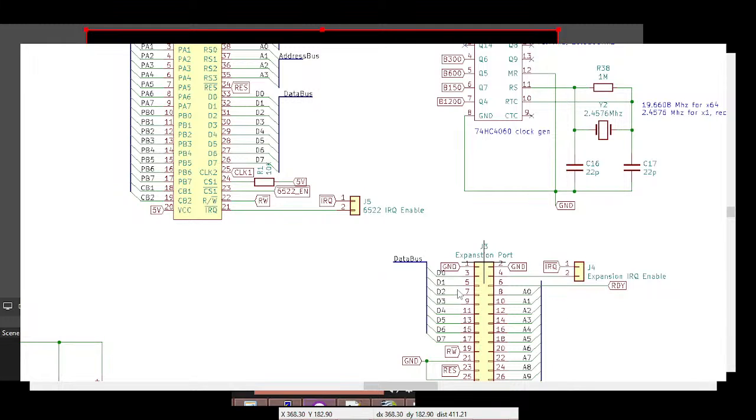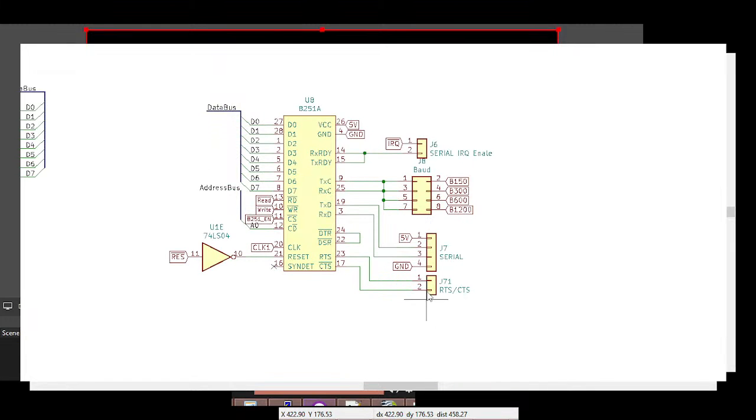We don't need that. And the 8251, which is an Intel serial port. It has a logic high reset, so we have to invert the reset on the logic low side for the 6502. And you've got serial coming out, and you return request to send, clear to send signals, and they are not being used in hardware, so it's all controlled via software, and it's just an old feature. We could just bridge them if we want to. The same with the DTR, DSR. It's either done in software or hardware, and I've just bridged it to be safe. Yeah, we don't need that.